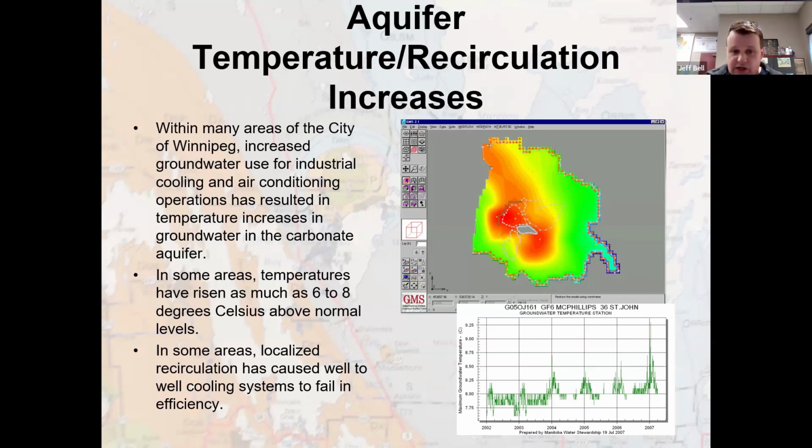Somebody has told me as well that sometimes the deeper foundations that tend to be piled down to the bedrock levels tend to create a little bit more heating of the bedrock, so we do tend to see a little bit higher levels. Sometimes those systems can recirculate as well, which results in the system not working. The big thing on that one is spacing between the wells and having an understanding of the transmissivity.